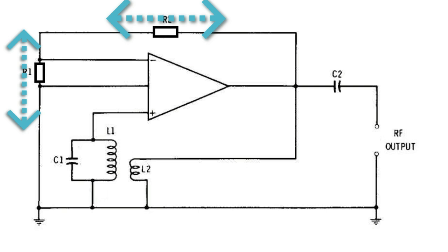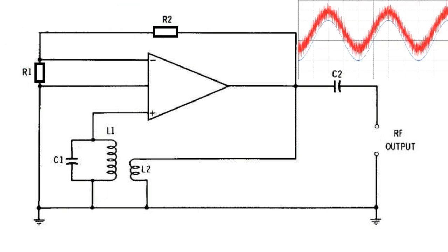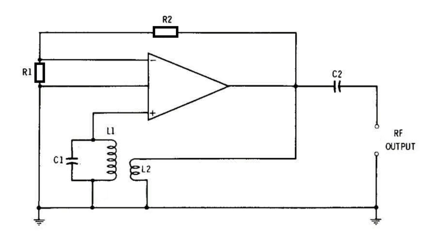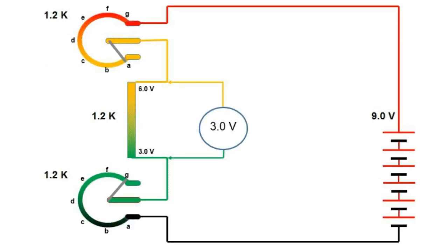This negative feedback helps to stabilize the working of the op-amp oscillator and minimizes the output signal distortion. But this negative feedback needs to be correctly balanced by appropriately adjusting the values of R1 and R2. This is important to ensure that it doesn't terminate the positive feedback and in the course destroy the oscillation.